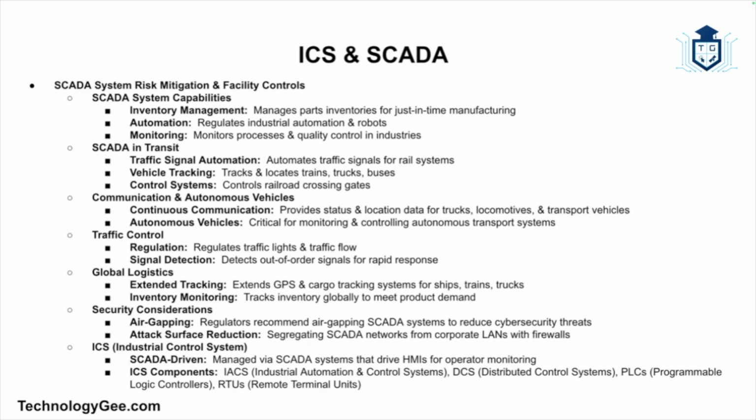threats. A key mitigation against attacks on SCADA systems and ICS is to reduce the attack surface by segregating the SCADA network from the corporate LAN with a firewall. And ICS is managed via a SCADA system, and SCADA systems drive HMIs for operators to monitor the status of a system while in the field. Other ICS components include industrial automation and control systems, distributed control systems, programmable logic controllers, and remote terminal units.